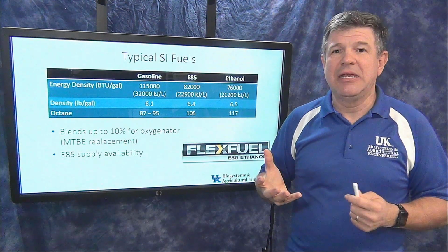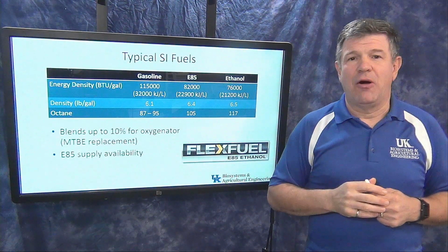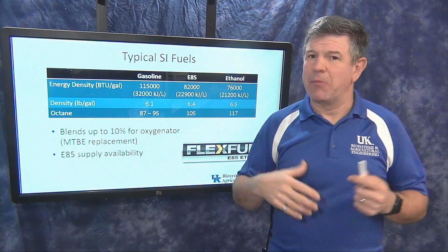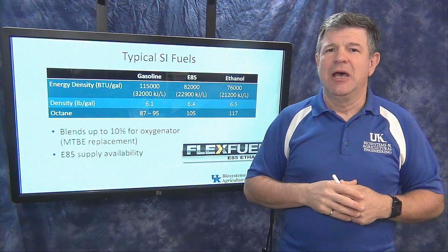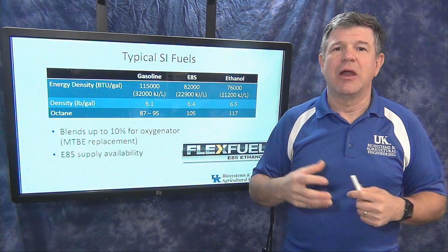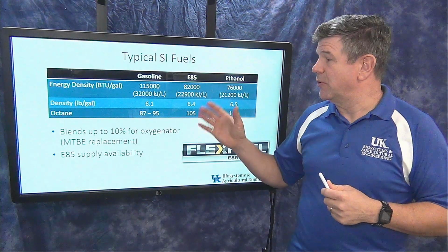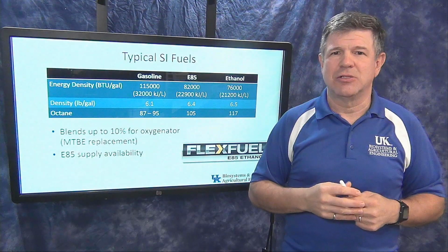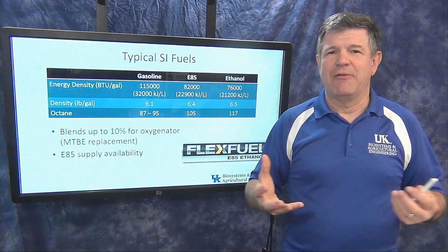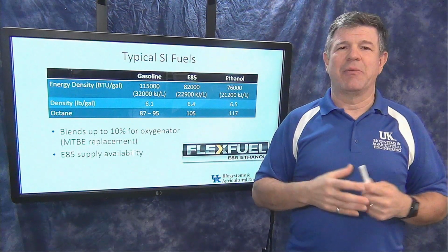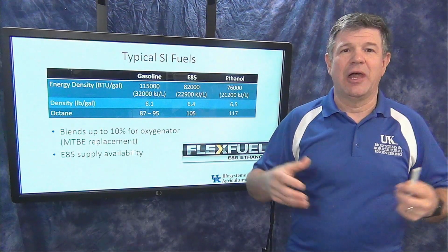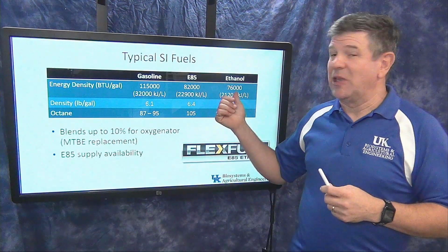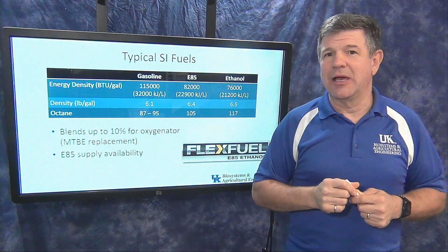Now, you can get non-ethanol fuel, and there's some reasons for that. Marine applications, for instance, it's very common to have non-ethanol fuel, so you want to make sure your fuel doesn't have any ethanol in it. And part of that has to do with the storage containers. A lot of boats have aluminum or fiberglass storage containers so that they're lighter, and ethanol likes aluminum and likes fiberglass.